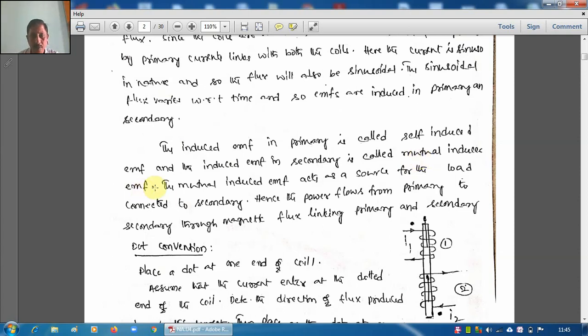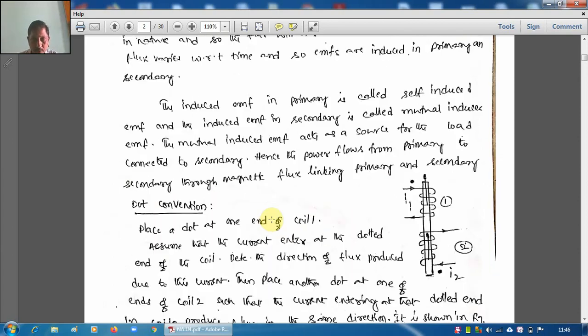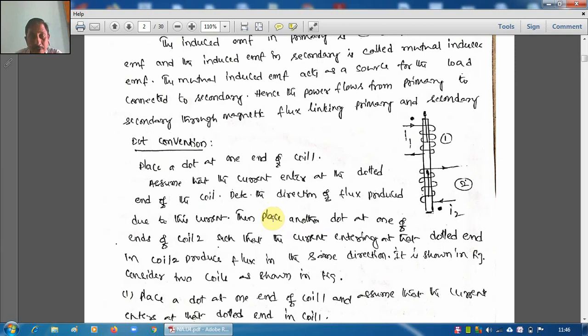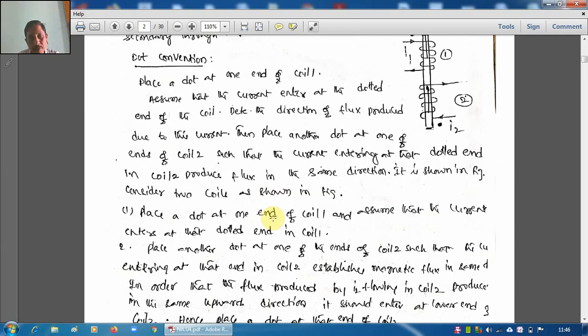This is because of the mutual induction from the other coil. Both the EMFs are induced based on Faraday's law, but there is a slight difference. In the first coil, as current is flowing in that coil itself, that is called self EMF. In the second coil, the current and flux are because of the first coil, so the EMF is mutual EMF. So these are the two EMFs. That is about the self-induced EMF and mutual induced EMF in coupled coils or a transformer.